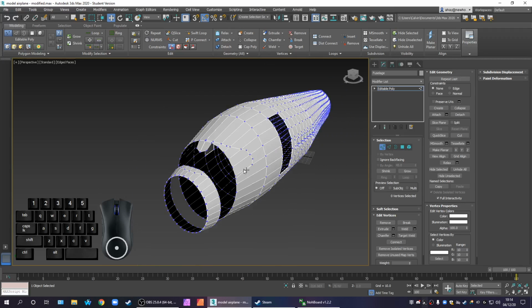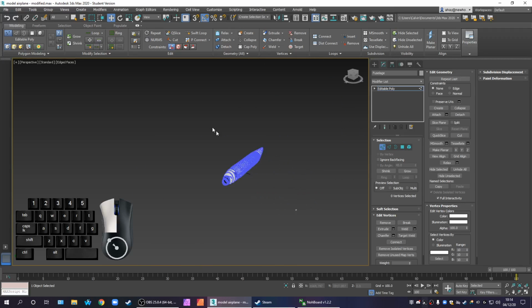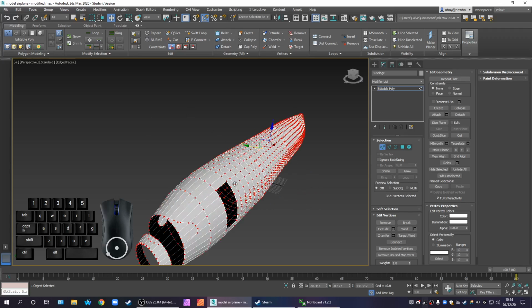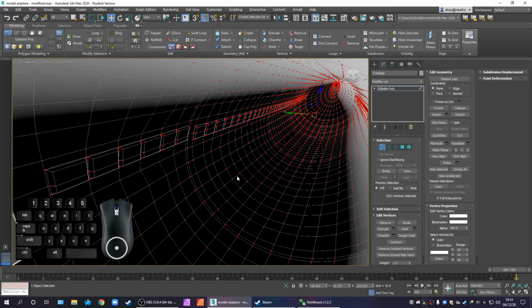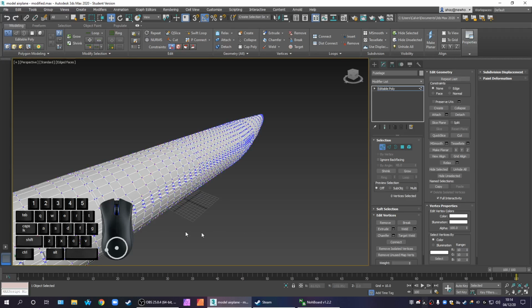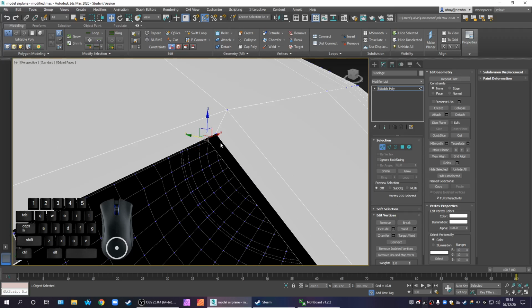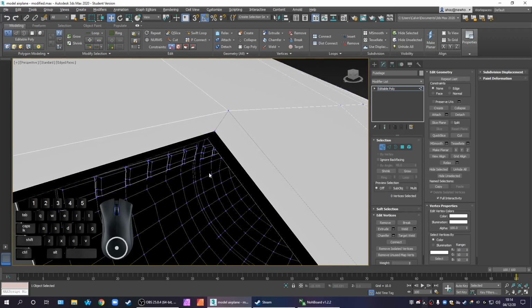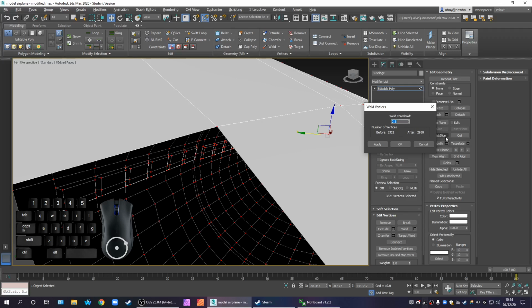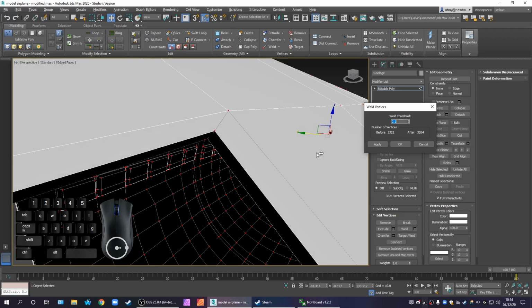Turns out I have a quick solution for this because we don't have too many very fine details on the aircraft. Probably our nearest spot we have like one vert and another is this doorway. So if I just zoom in on this and then I select all the verts, Control A, and go to weld, I can set my weld threshold high enough that it starts messing with this door, and then I obviously don't want that. So if I go down to like 0.1, everything's fine.